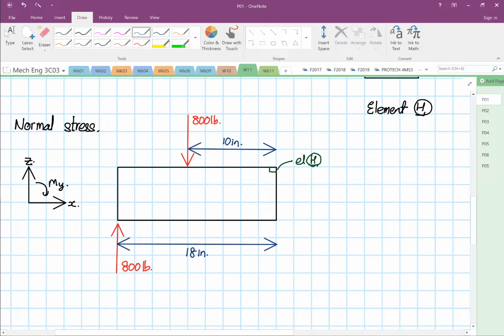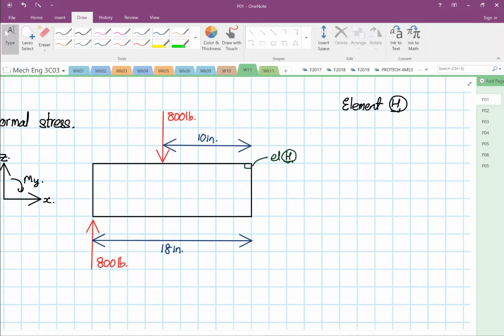Right? And then we are going to assume, for those of you who are not mechanical engineers, that's fine, we're going to assume positive shear and positive bending moment. What this means is we're going to assume that we have a shear force coming down in this direction. So this is our V at point H. And then we have a moment at point H going in that direction.